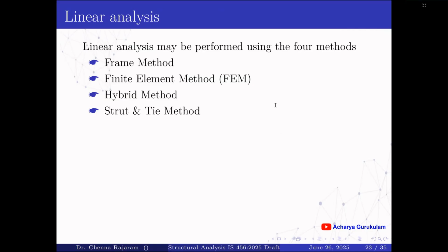The hybrid method shall be considered when structures consist of mixed structural systems and members of uneven geometry, that is, D-regions such as beam-column joints with similar sizes. Some members may be modeled as frame members by their centerline geometries. All requirements related to the modeling of the structure specified in the frame and finite element methods shall be applicable here.